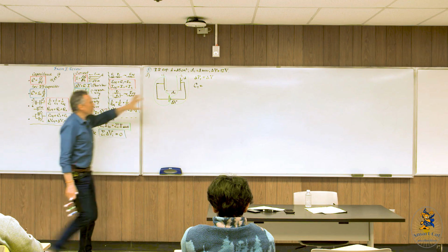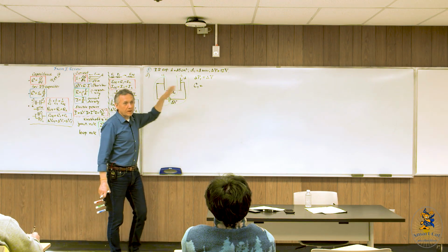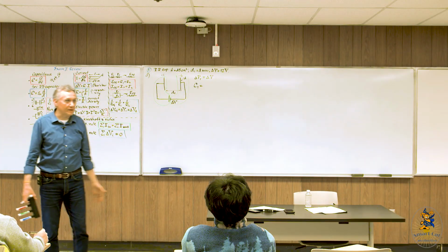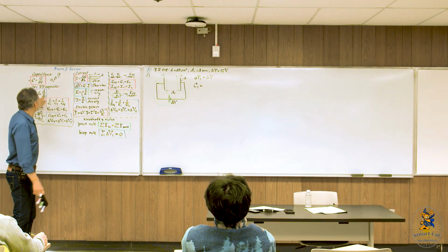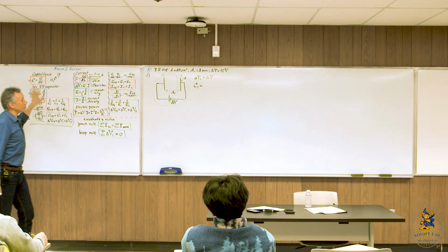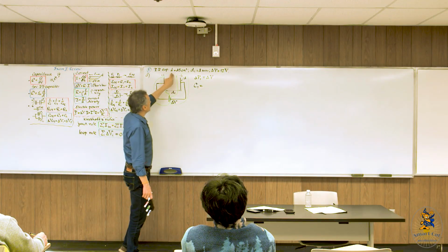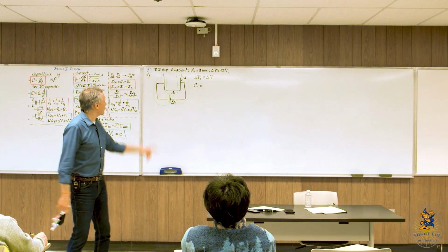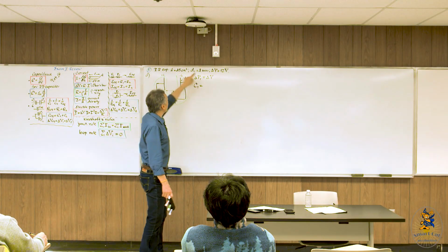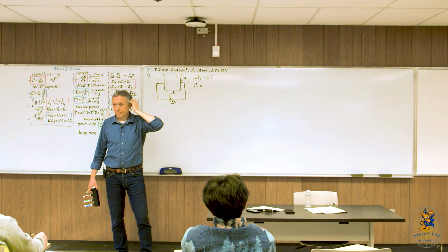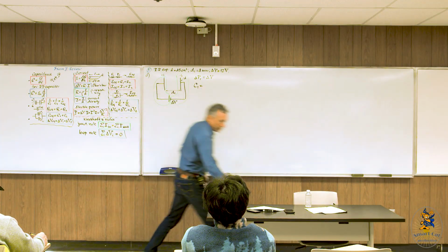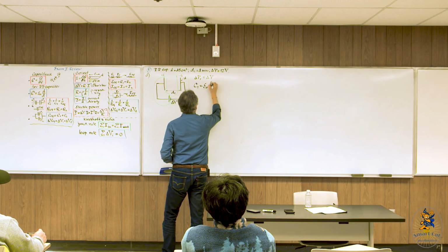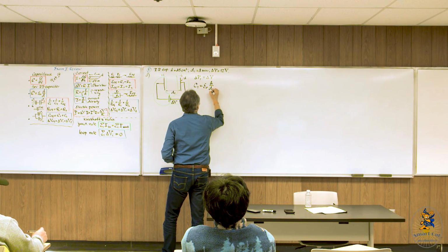Of course, what's also important is what's between the plates, but in this course we have vacuum between the plates, the system is in a vacuum. So we just need to know geometry, and geometry is given. Area is given, spacing is given, so we should be able to calculate. But all these parameters must be converted into meters. So it will be epsilon naught A over D1.